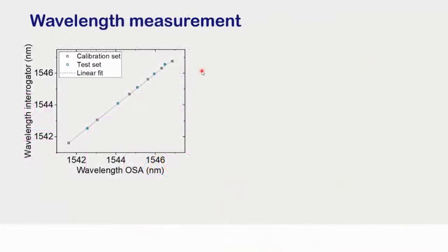Okay, the next step is to build a prediction model. In this case, we don't use any fitting or anything like this. We just take the 4 currents and train a model. We produce a shift of the peak, and we measure it spectrally, say, with an optical spectrum analyzer. Then we correlate this with the 4 photocurrents, and we build a prediction model that allows us to predict the wavelength based on 4 unknown currents, and that's basically on a least square principle.